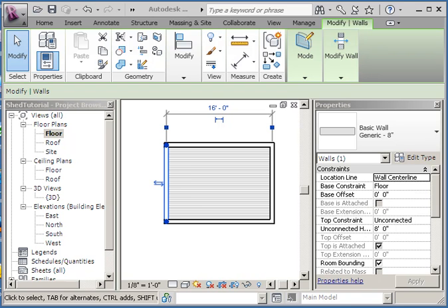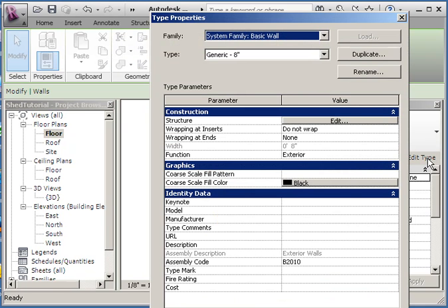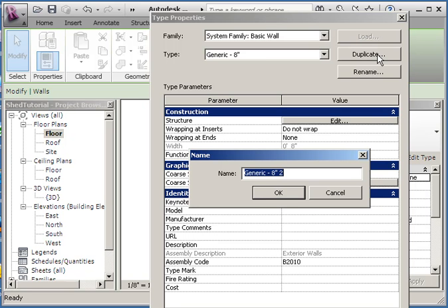In the last lesson we were looking at the roof. In this lesson we're doing step 9, modify wall type, and we're to the point now where we're getting ready to change our wall material. So we're going to pick it up on step number 2, select one wall in the properties palette and select edit type. So we're selecting here for edit type, and we're going to change the type of wall, then press the duplicate key. So we're duplicating the wall and we're going to name it shed wall.